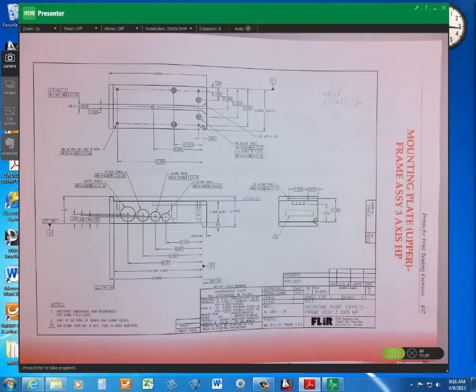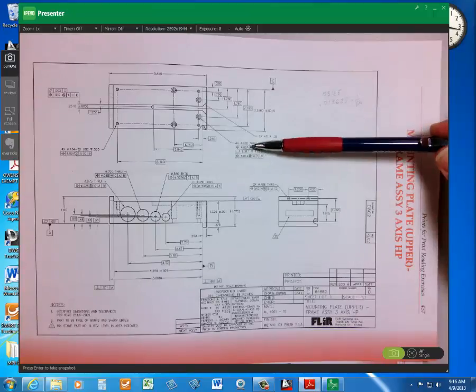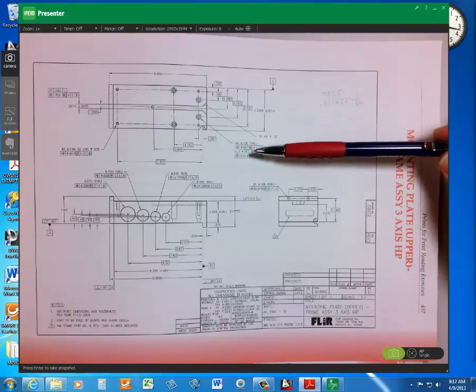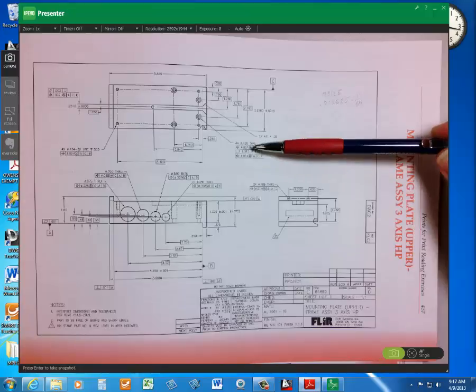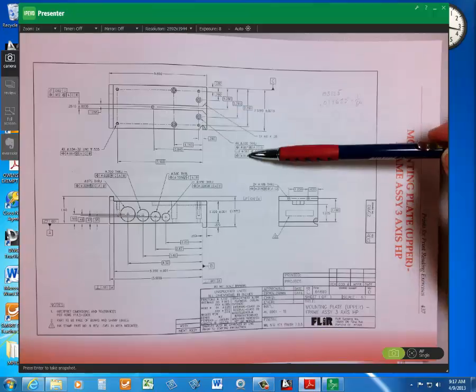The position requirements are tighter for the hole. The hole is listed first right here, and it's 7 thousandths. That doesn't fully answer why there's a separate feature control frame, except that we want to control the hole differently than we do the counterbore.